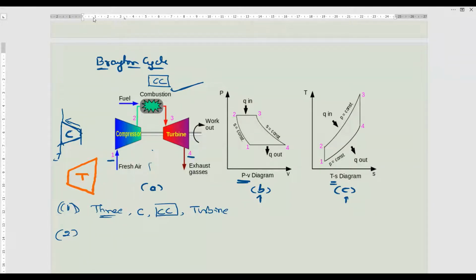The difference between the turbine and compressor is that in the compressor the area is gradually decreasing. In the turbine, the inlet is shown here and the area gradually increases, and the outlet is at this point. One more difference in the symbol: the turbine will show the shaft on the right, the generator. In the compressor, we will show the shaft on the left hand side.